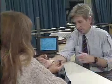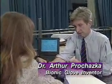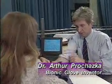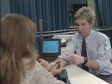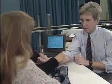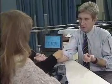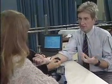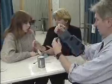So what are the amounts of voltage and current? Well, the pulses you can hear, the clicking, are pulses of about 30 volts. And that's between this electrode and this electrode. But that's like pressure in a tap that's closed. Opening the tap is equivalent to making contact with the skin, and now those pulses of current are flowing through my skin. So about 30 milliamp pulses, 30 volts, that translates into a resistance of about 1 kilo or 1,000 ohms.